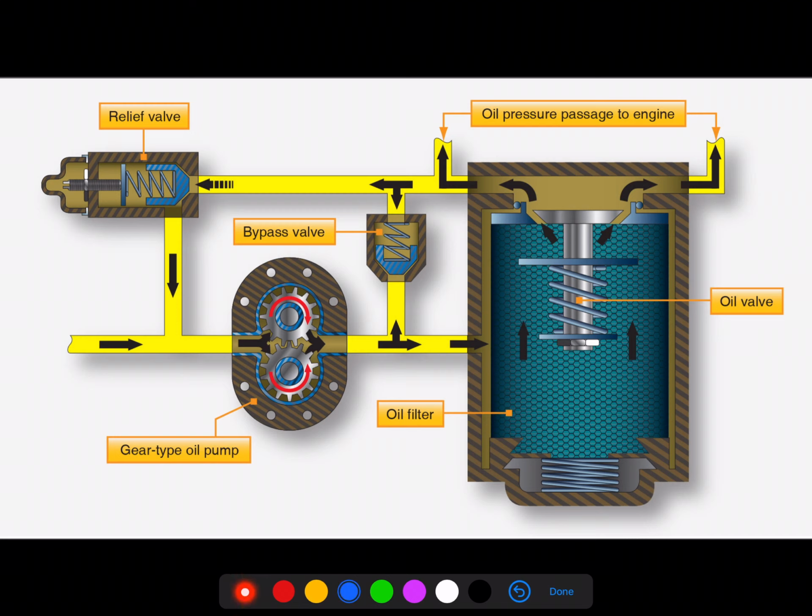With other systems, we don't have this adjustment spring to be able to make adjustments to our operating pressure. Instead, what we have are washers that are stacked underneath this plunger on the spring to regulate the tension of that spring, thereby changing the unseating pressure it takes to allow oil to go into bypass through that relief valve.